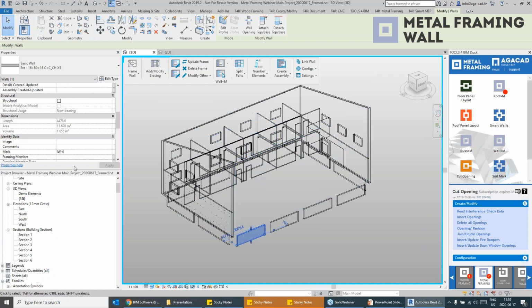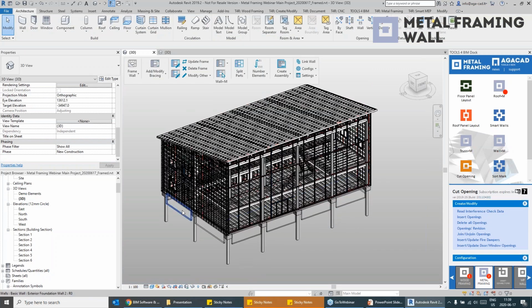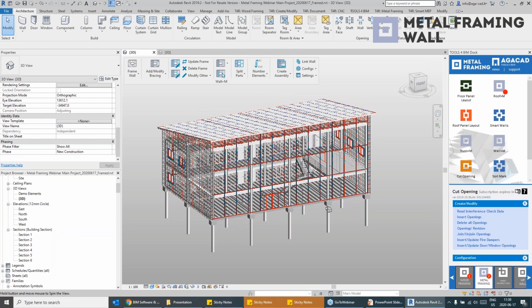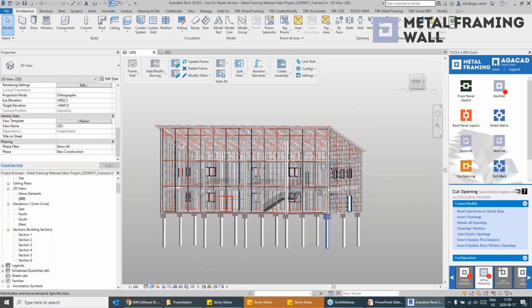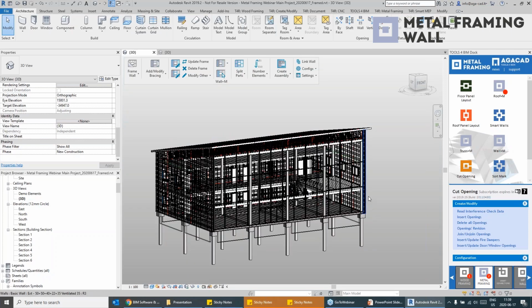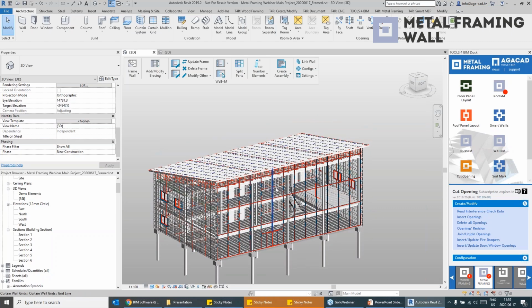And my exterior walls were getting EW. Of course, I can create more complex rules to have foundation walls named differently, as well as a rule to set the mark also including the level number or department letter and so on. As you can see, it can be numbered. And whenever everything is numbered, you can just go and create shop tickets for those frames.